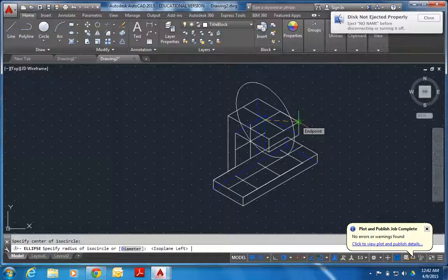So if we press function 5, we can kind of change this around. And you can see now that my cursor has changed its directions. Now that the cursor is parallel to the two axes that it intersects with, that's the one I want to use. So now I just type in the radius of the circle. On our document it says a diameter of 30. Obviously radius would then be 15. So I'm just going to type that in and it goes right to the scale.